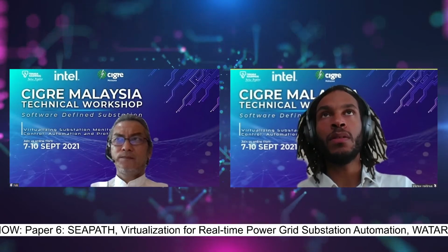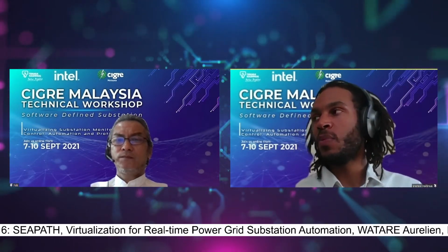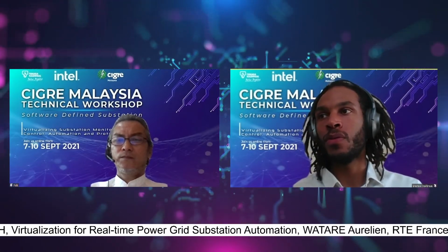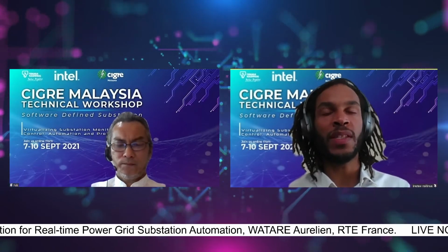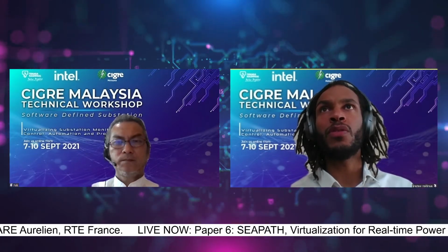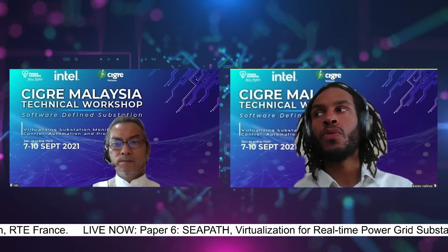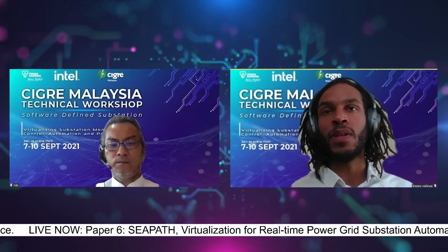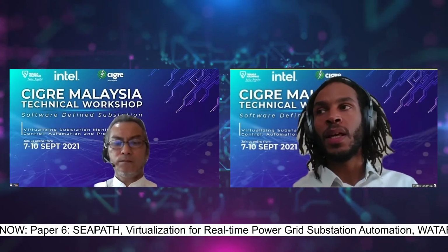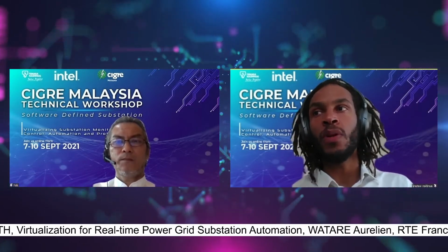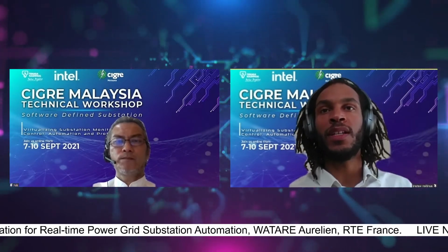in a virtual machine, it's a really complex question because it really depends on the input output. You can have your application run fast on a VM. If we talk just about the application without input output, today I think the minimum we achieve is 66 microsecond latency. But you have lots of configuration to make to not have issues with the network as well, because it's 61850, so you will receive data from the network. And right now we are working on this part too. So low latency network and low latency virtual machine, both are connected, of course.